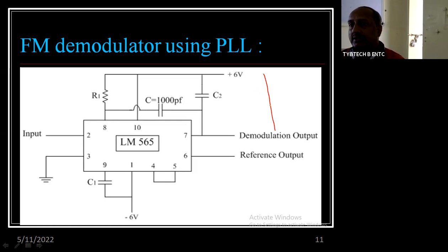If you see here, the FM output looks like this: somewhere it has high frequency and somewhere it has low frequency. So compression and rarefaction is the concept in this FM. Where we get compression and where we get rarefaction, we should also know, because that is the base of detection, the opposite process in demodulation. Compression happens for the positive half cycle of the modulating signal.